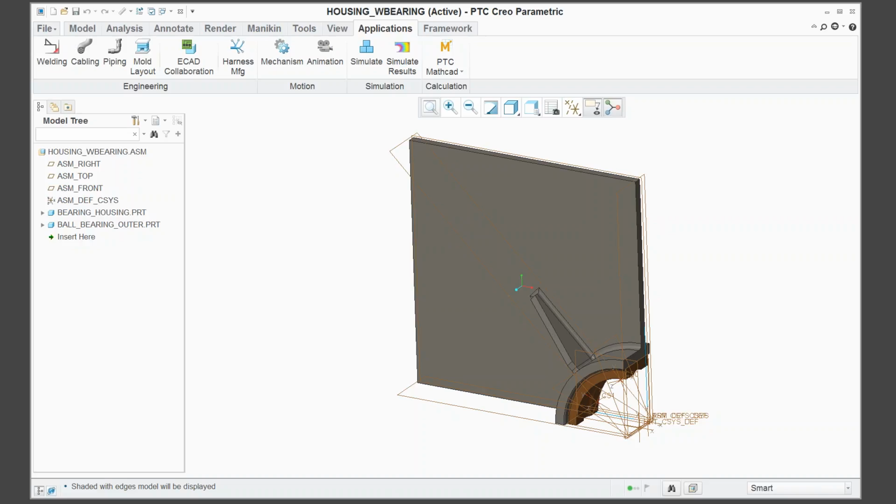Now, one of the problems that we often run into in FEA is figuring out how to constrain parts. And usually if I find people that have made erroneous results, it's because they over-constrained or somehow didn't properly constrain a part. So one of the solutions to that is to do the analysis in assembly mode where the parts are realistically mated to their mating parts and you're analyzing the whole works. So any bad assumptions are far enough away from the area of interest that it's not going to affect your conclusions much. And that's what I'm doing here.